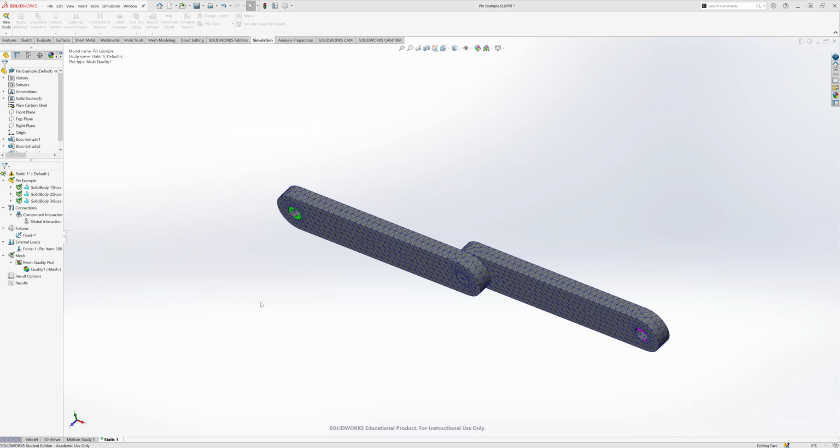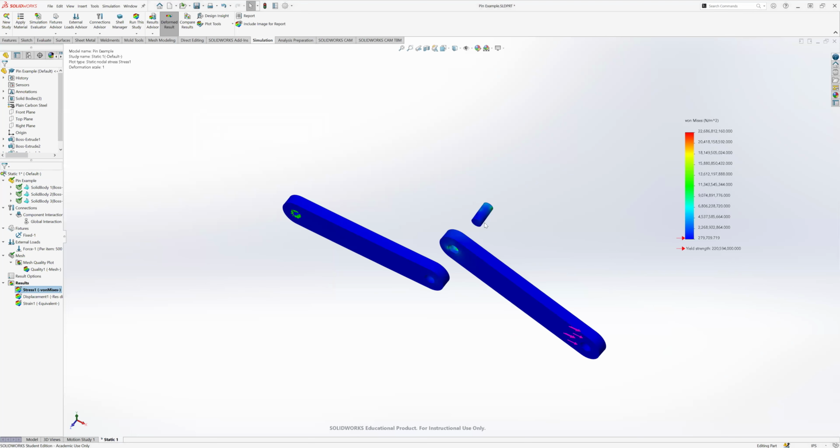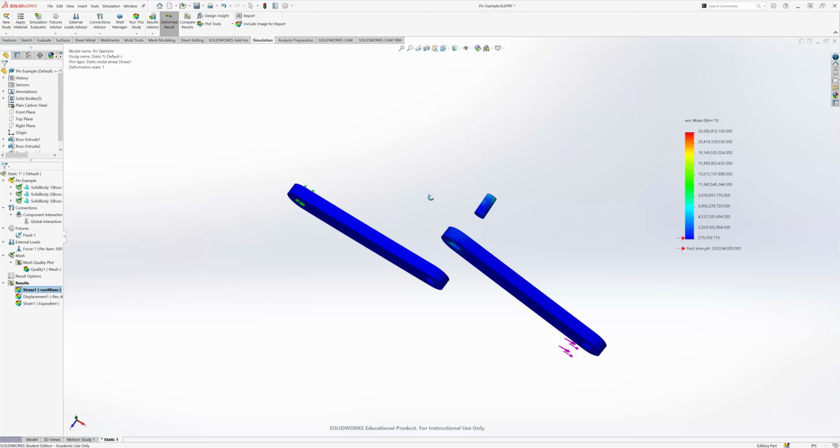And what will end up happening, this simulation will still fail because either the pin or this component here is just going to probably fly out into space. Because even if you have a very, very small unbalanced force, I'll say no to the... yeah, so then you'll end up with something like this. So if you ever have something like this happen, then in this case, we know that this is obviously not the behavior we're looking for.